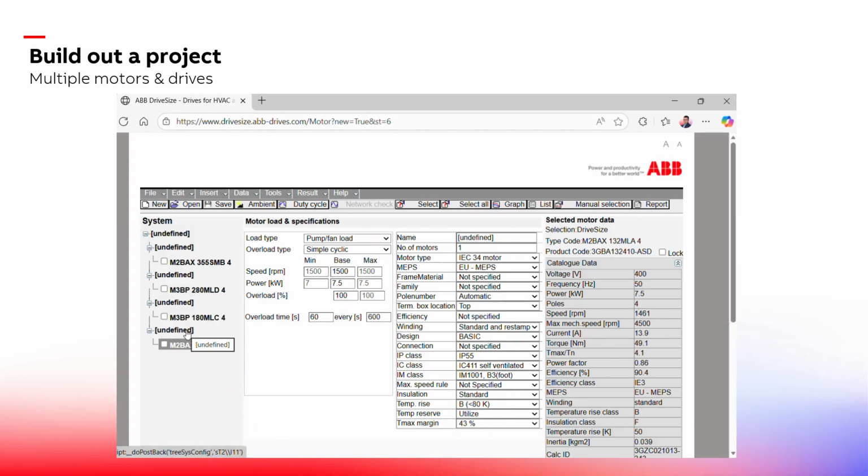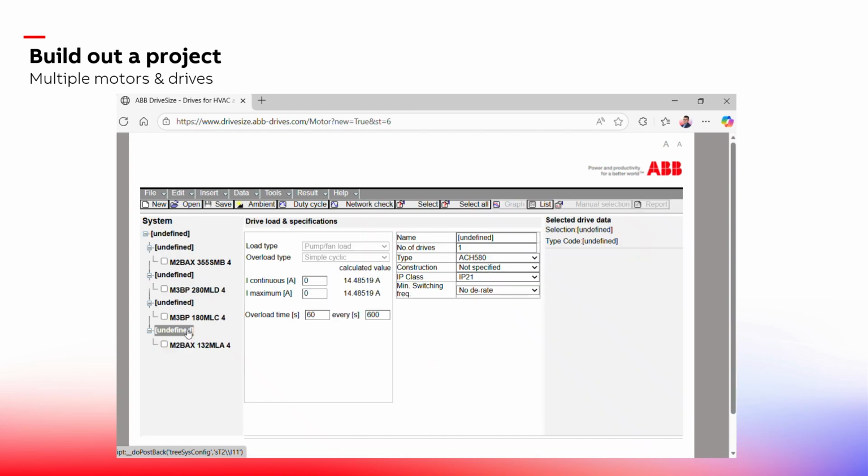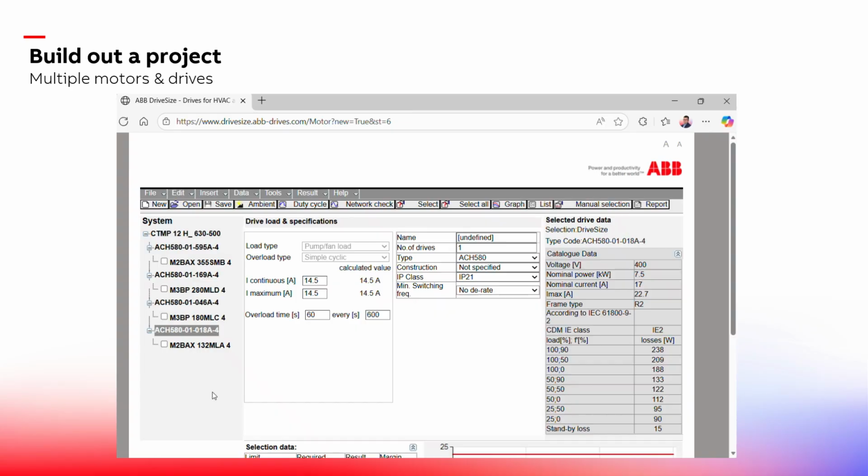Now, what we're going to do now is size the drive for each one. So if we go to, we can actually press select all. This will give you a good demonstration of what select all does. Now, what select all does is anything that's undefined, it selects everything left in the system tree. So because we've left everything as standard, it selected all 6 pulse options for all the actual drives that are left for each one. As you can see as we go through these,